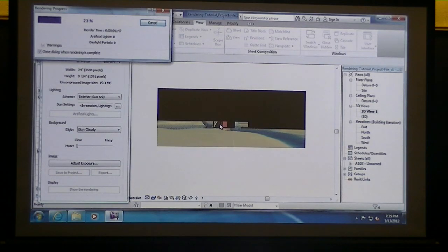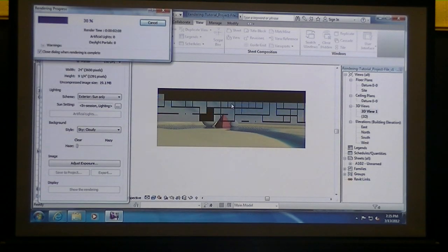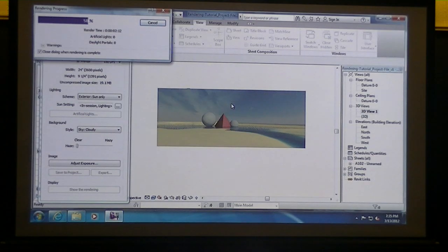Another item when you're rendering, which you probably know from most other classes, is go into your Windows settings and turn off your screensaver. Don't make your screensaver pop up, and also make it so that your monitors don't ever shut off. You have those power settings under the control panel, because sometimes this is using pretty much every resource it can from the computer, and as soon as that screensaver comes on, it might lock up your computer, and you might not be able to get this rendering.